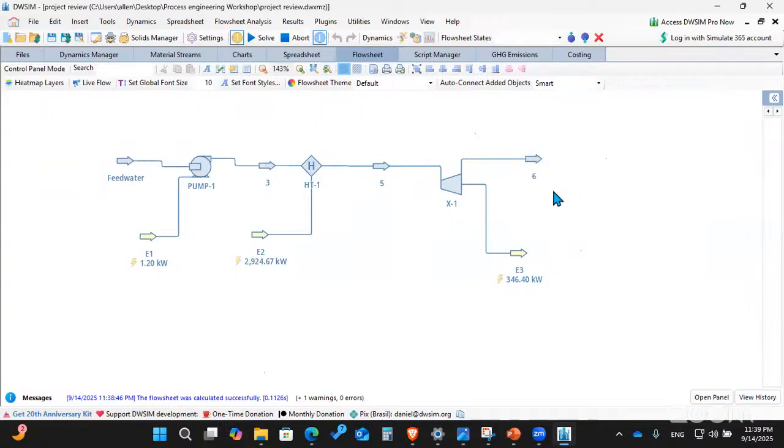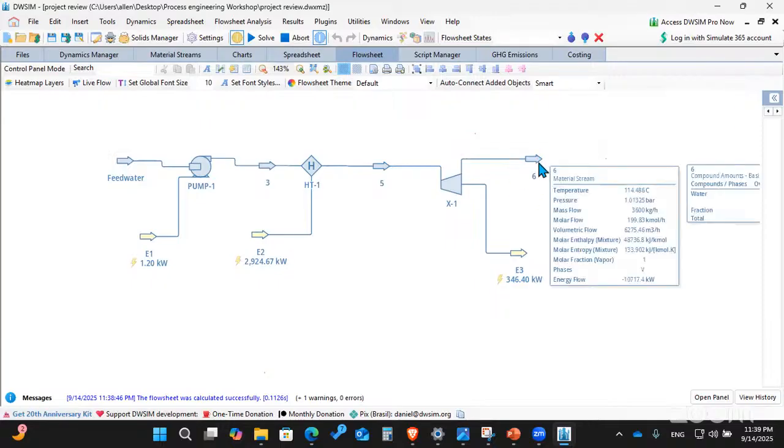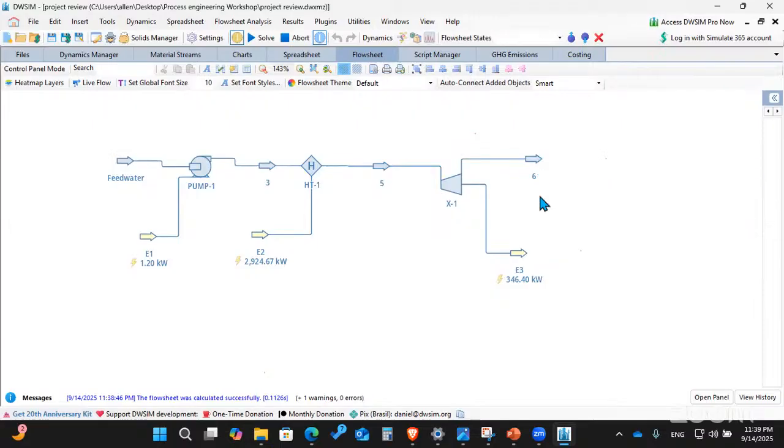So how do we recover all that we have? We need to recover this steam. We need to make use of this steam, and either we use it to supply other utility, probably sending it back to the feed, but not at the feed water, but probably at the inlet of the heater, right? So now, how do we go ahead to optimize this operation?